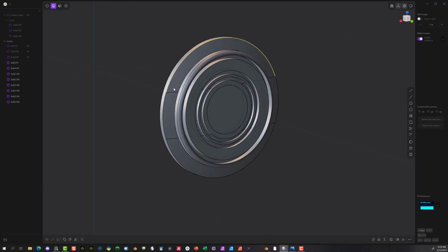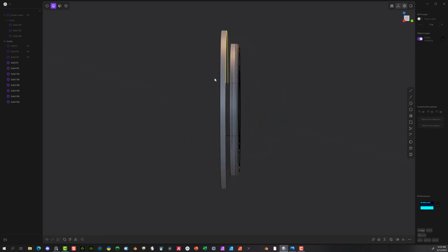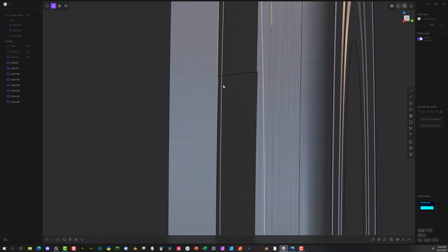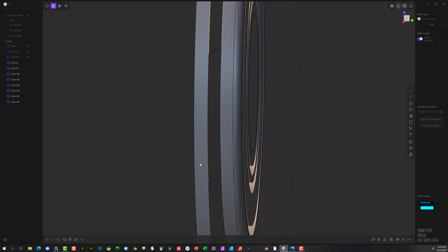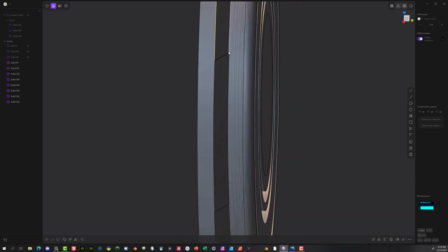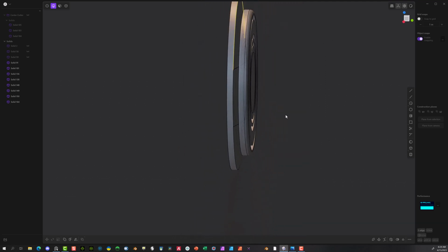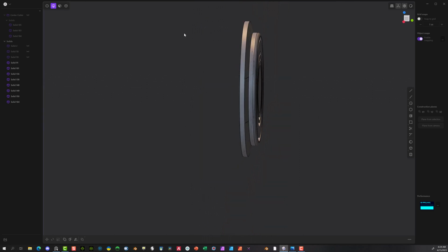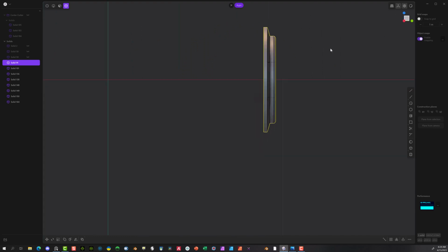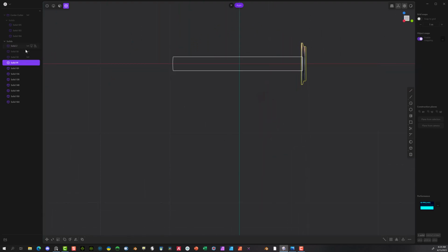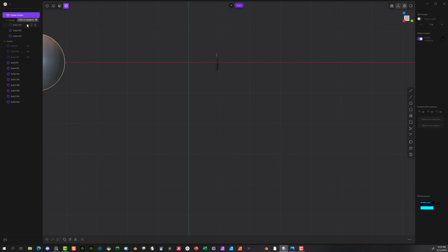And what I want to do now is I'm going to go ahead and maneuver this a little bit. So for some reason these are not the way I'd like them. They seem to be off a little bit from each other, just causing a little bit of problem here. So this intersection is not lined up with the edge is. So one way to solve this is to cut this again. So I'm going to use the solid tool and I'm going to go to the x-axis and I'm going to create or unhide one of those balls that I created earlier, which is one of these, and select this one and one of these.